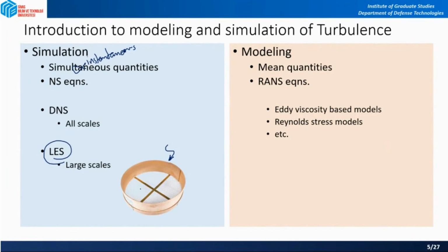So when we filter the data for LES, the mathematical filtering operation will give us a filtered equation that retains only the instantaneous condition of large eddies. Just remember that we had the Reynolds decomposition, where you decompose instantaneous velocity into mean velocity and fluctuating velocity.